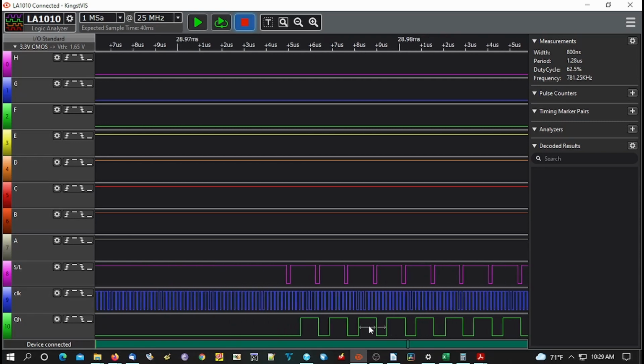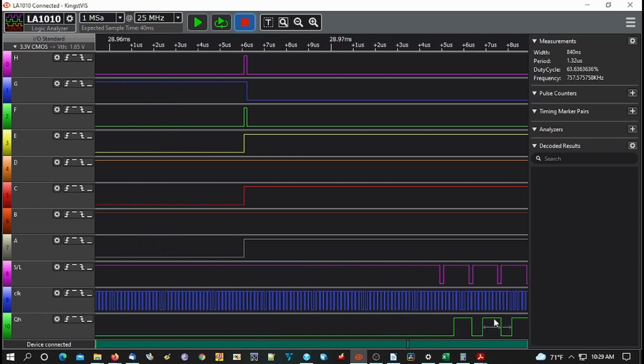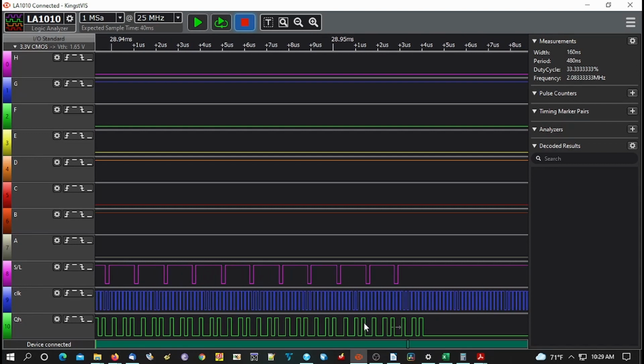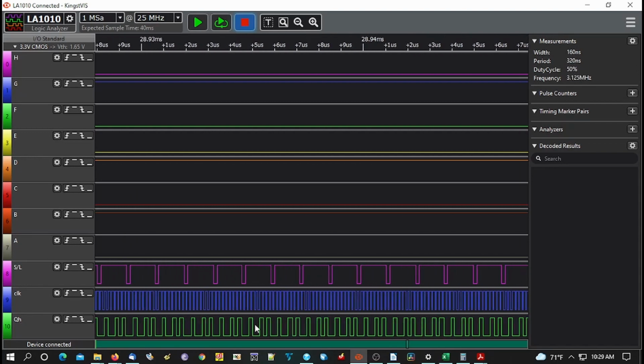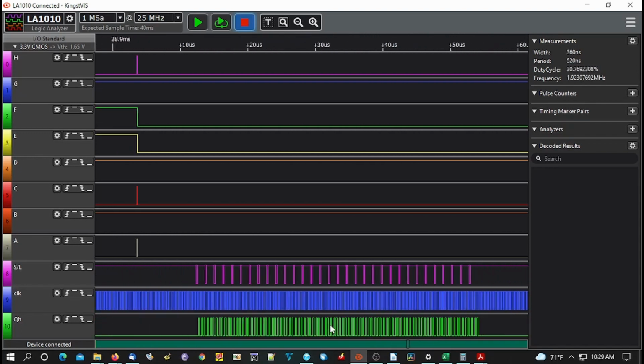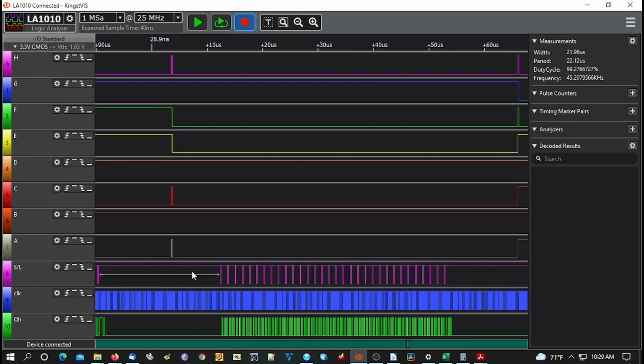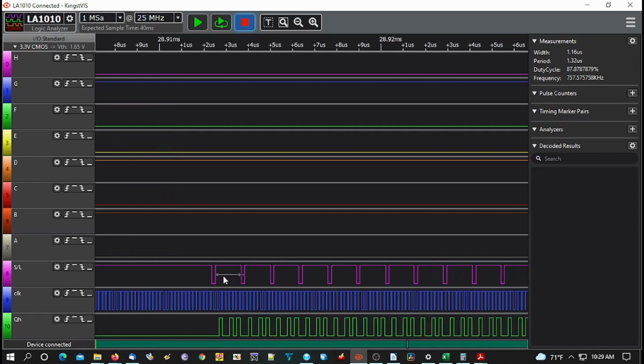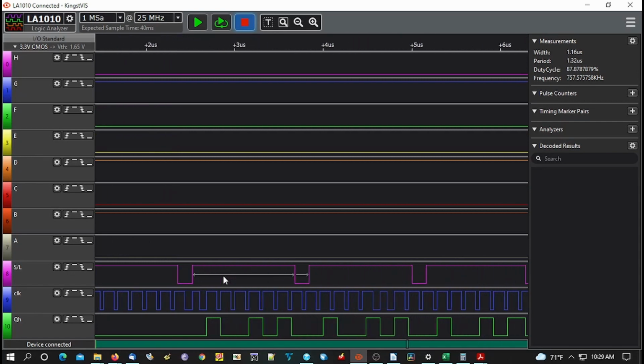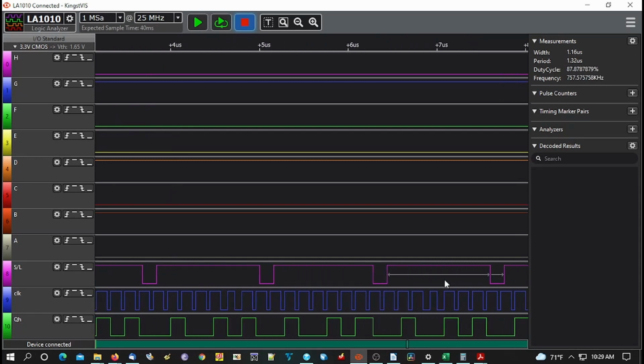This must be something to do with the loading from the ROM chip. It doesn't affect anything, since those blips are there during the H-blank portion of the triggering. You can see that the green output serial bits are between the pink load portions, as we'd expect.